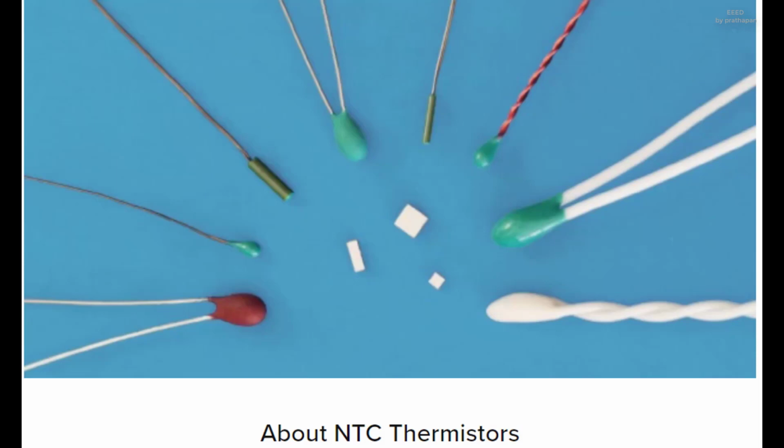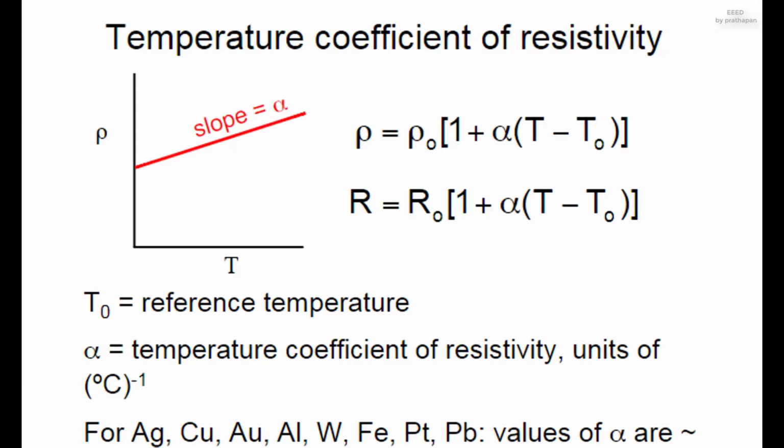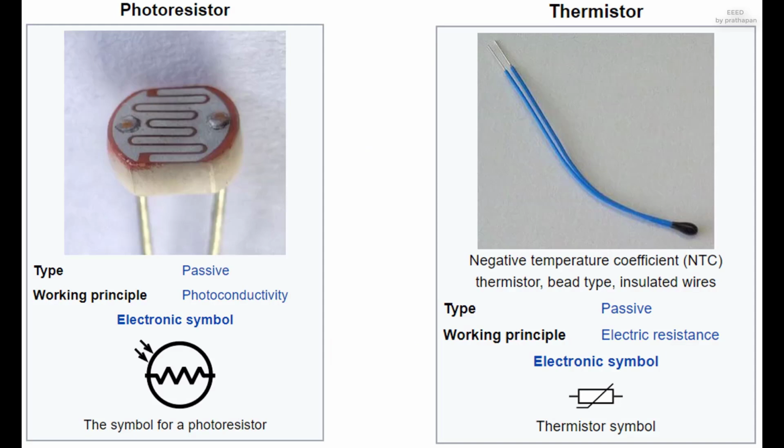Special devices. There are various devices whose resistance changes with various quantities. The resistance of NTC thermistors exhibit a strong negative temperature coefficient, making them useful for measuring temperatures. Since their resistance can be large until they are allowed to heat up due to the passage of current, they are also commonly used to prevent excessive current surges when equipment is powered on. Similarly, the resistance of a humistor varies with humidity. One sort of photodetector, the photoresistor, has a resistance which varies with illumination.